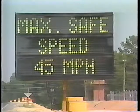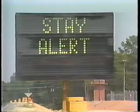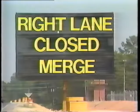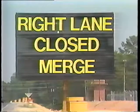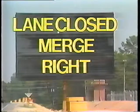When using a changeable message sign, be sure the message is clear. A lengthy message may distract the motorist too long. The word order in a message can also cause problems. For example, "right lane closed, merge" would get a different driver response than "lane closed, merge right." Yet the messages are similar, except for the beginning point.